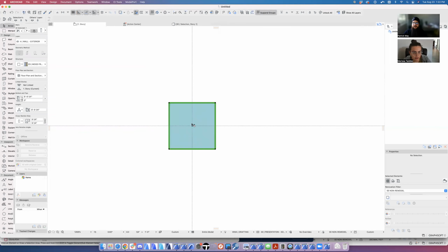Now I have this set to origin at 0, 0, and this is a critical part because we're actually going to get into a little bit of GDL scripting. It's not overly complicated. We just need to isolate out a couple of script commands and do some copy and paste. Because really what we want to do is take our 3D component and a 2D component and combine those two together. So I have my light fixture here.